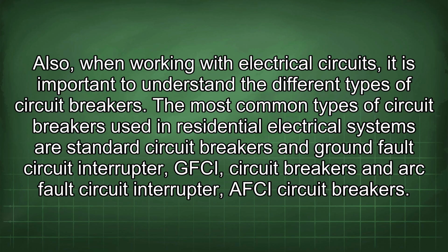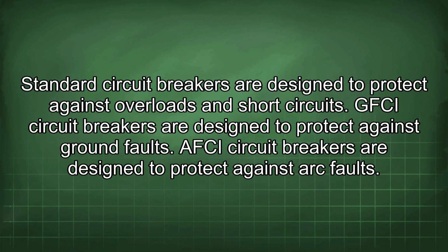Also, when working with electrical circuits, it is important to understand the different types of circuit breakers. The most common types of circuit breakers used in residential electrical systems are standard circuit breakers, ground fault circuit interrupter (GFCI) circuit breakers, and arc fault circuit interrupter (AFCI) circuit breakers. Standard circuit breakers are designed to protect against overloads and short circuits. GFCI circuit breakers are designed to protect against ground faults. AFCI circuit breakers are designed to protect against arc faults.